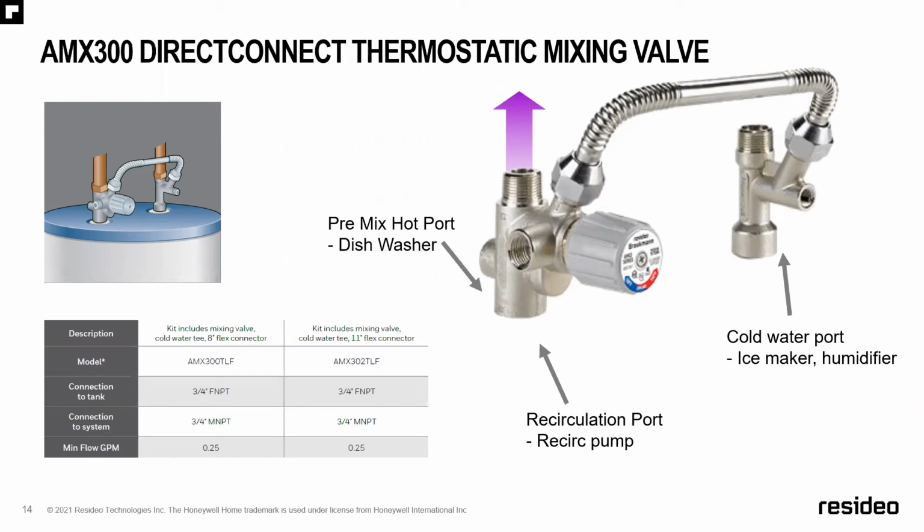These are very user-friendly mixing valves that have a couple of different features. One of the features, at the top, is a pre-mixed hot port. So again, let's talk about sterilization. You can't sterilize things with 120-degree water. You have to have at least 135 to 140 to sterilize. So we have that port for that requirement if need be.